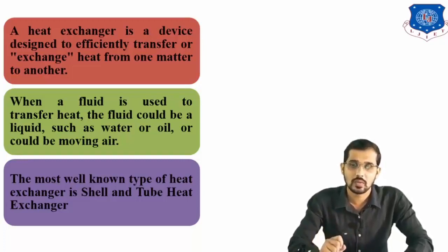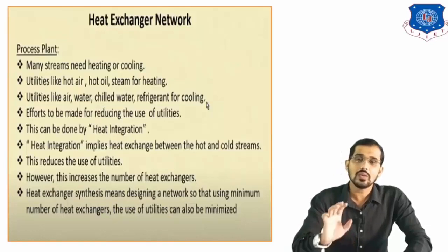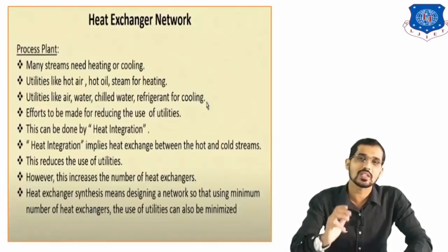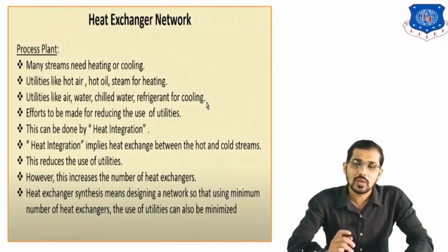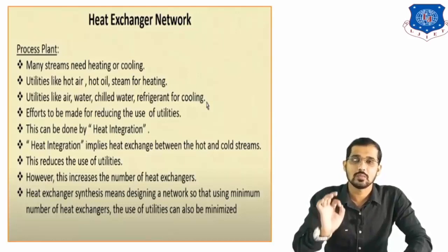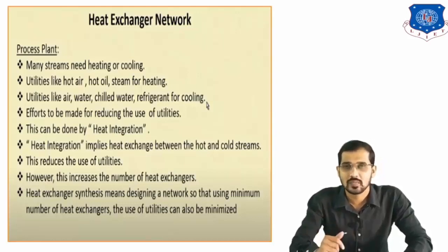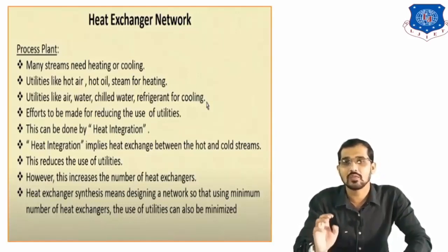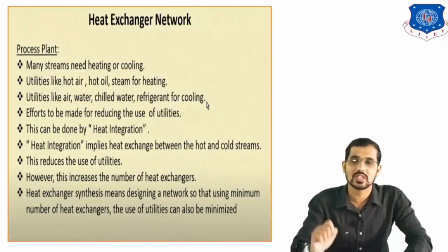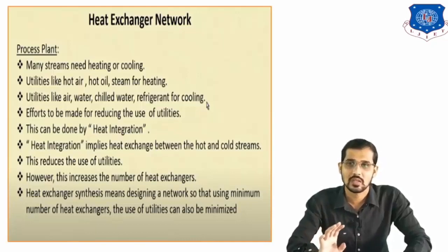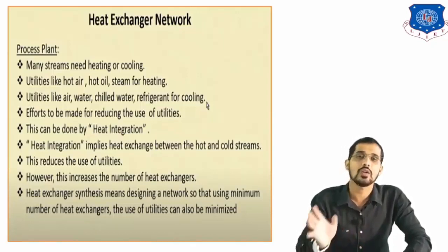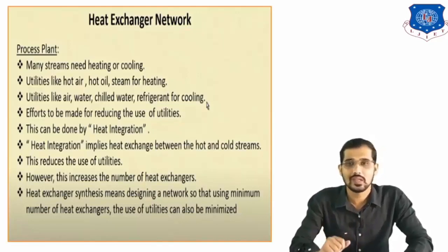So you can see now in this lecture I am going to discuss with you the heat exchanger network. What is the significance of heat exchanger network? Why is this necessary? In chemical industry this concept is important to get process integration. Process integration is nothing but minimizing the various utilities which are used in chemical industries by using heat exchangers. Here we are replacing various utilities, cold utilities or hot utilities, by heat exchangers.